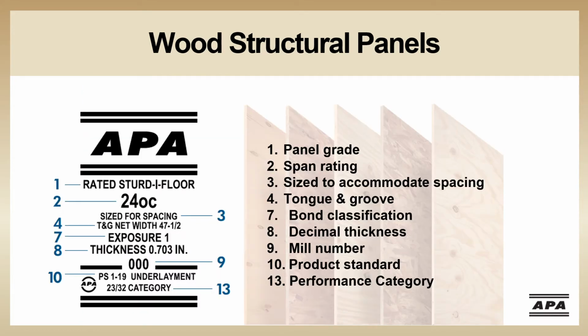What does the trademark tell us on this performance-rated panel? This image is from the latest Engineered Wood Construction Guide. First of all, the recommended application, which in this case is floor sheathing. Secondly, the maximum distance between supports that this panel can be used as intended according to the building codes. The larger this distance, the stronger the panel in resisting gravity loads.